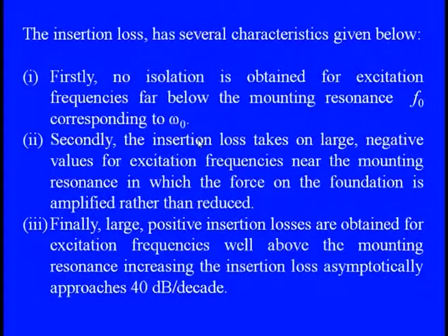So, certainly you see here we need to check that the insertion losses are now significant in this case. Finally, large and positive insertion losses can be obtained for those exciting frequencies which are well above the mounting resonances. The insertion loss asymptotically approaches even 40 dB per decade.